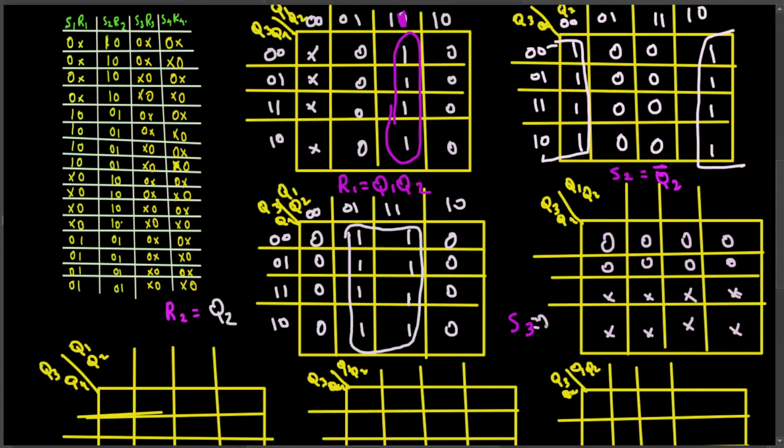That is one way. Another thing you can do is turn all these don't cares into 1 and write an expression for it. Let's see what the expression is going to be. But I'm going to use 0, because when you use 0, the final design is going to be so easy. If you have other things, it's going to make the circuit a little bit messy.